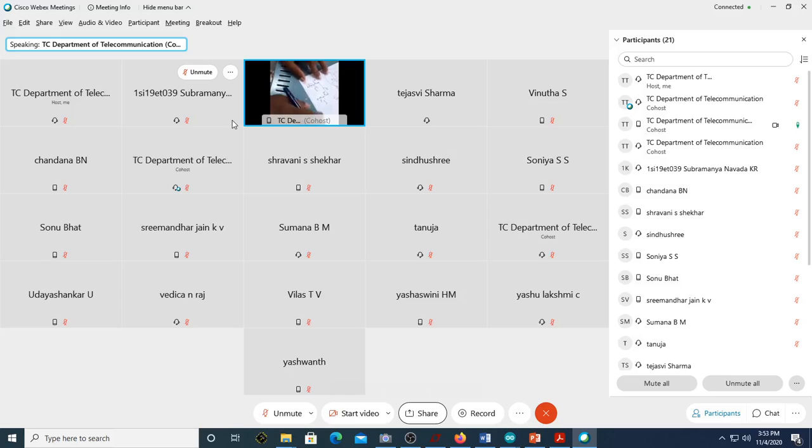Yes, sir. So the modification from slide switch to push button is this. This will go to whatever buffer pin number you have, 8 or 9. Correct? Yes, sir. This is a more realistic circuit where somebody just puts his leg on this button, it will be pressed and you'll get high. If he has not entered the other portion, it will be low. It is high, low, so the motor runs in a particular direction. When he leaves this button, this will become 0, 0. When it becomes 0, 0, after 5 seconds, it stops.